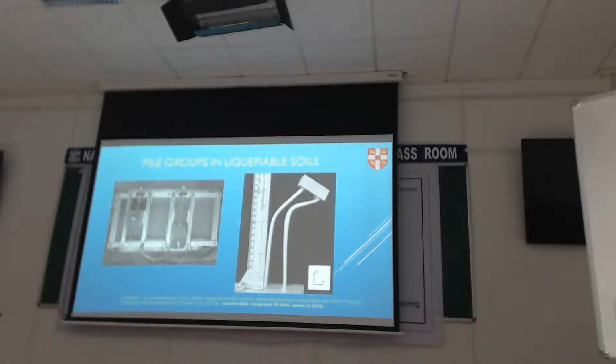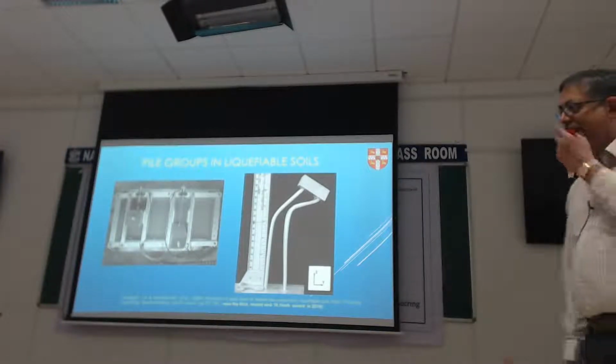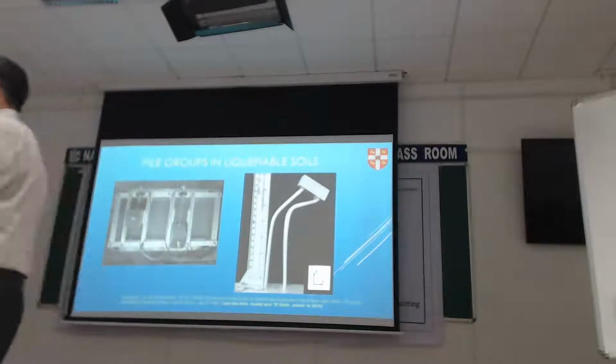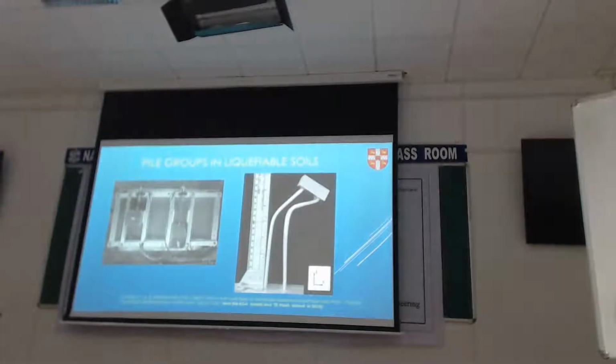Now count the hinges. How many hinges are formed? Really, one there, and one there, and maybe partially there. So this is reality. In theory, you can idealize the hinges quite nicely, but you can have partial hinges also, where some energy is dissipated. The lesson we learned from all this is that the hinges will form according to the plastic work equation.